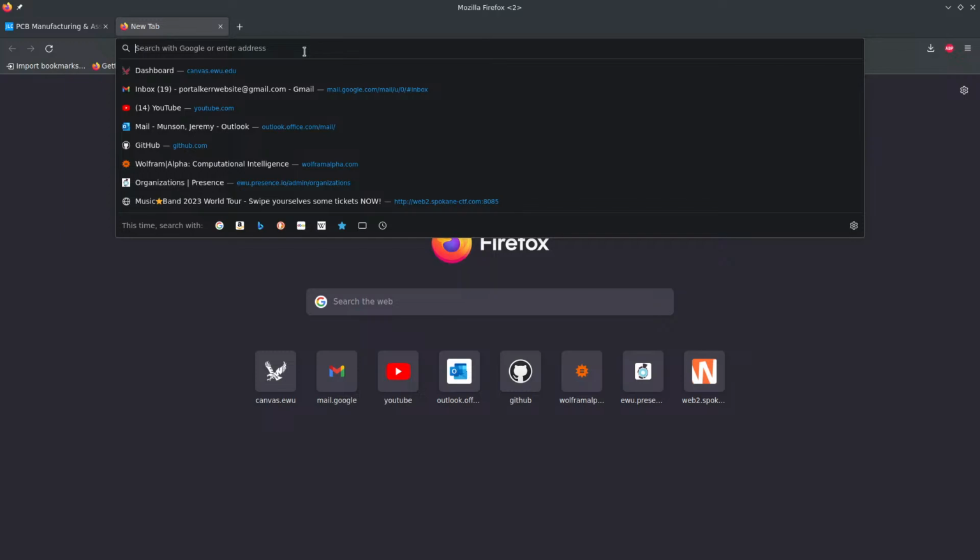Like I was trying to make a point earlier, they try to make the chips as easy to use as they can. So this chip takes as an input an interface, step and direction. If step is high, go one way. If step is low, go the other way. And then if direction is high, go one way. If direction is low, go the other way. And then every time it gets a pulse on the step pin, it advances your stepper motor one step. Do you know how stepper motors work?